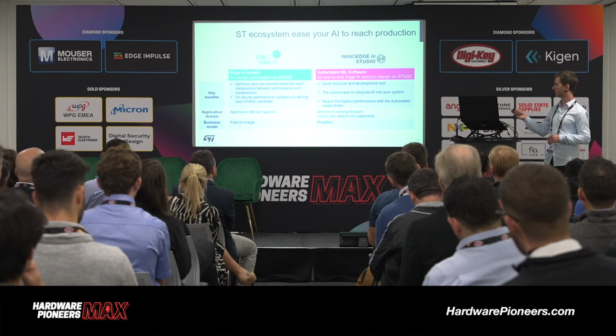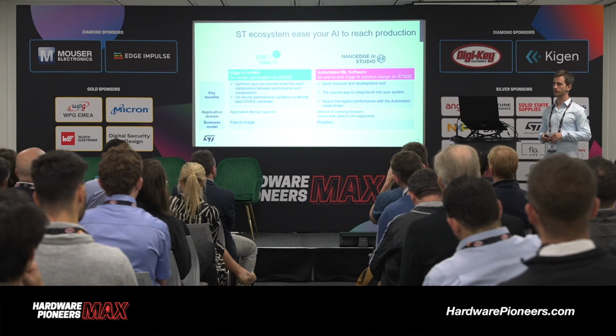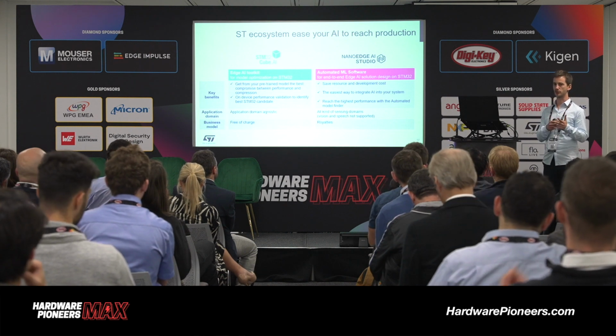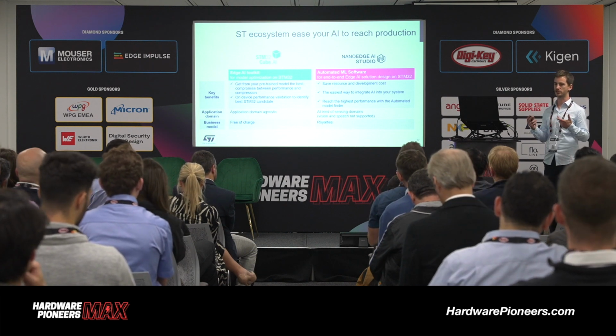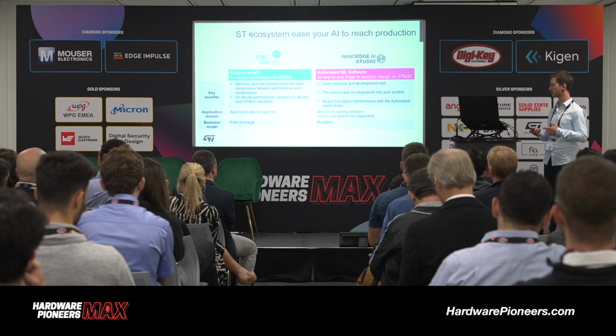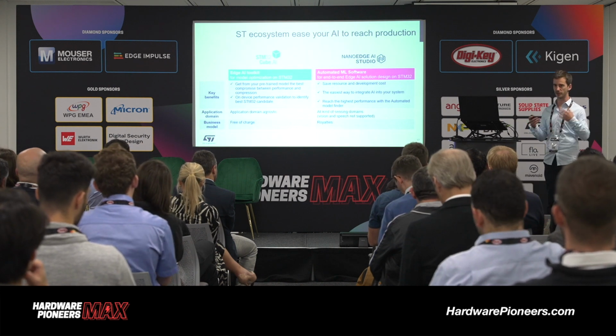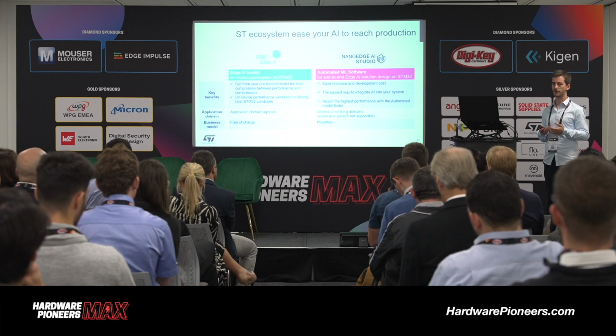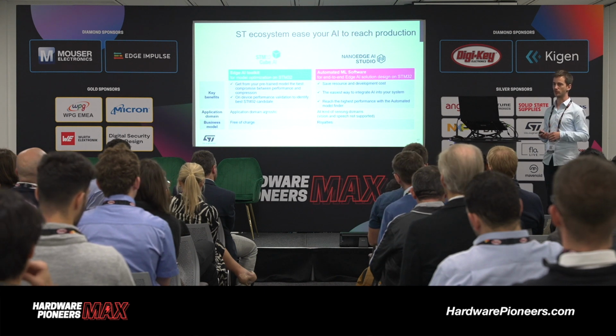On the other side, NanoEdge works for any sensor, really, like accelerometer, temperature, pressure, current, voltage, or time of flight, or a combination of these. Anything that is not too consuming for the microcontroller, like, for example, we would avoid image or speech.